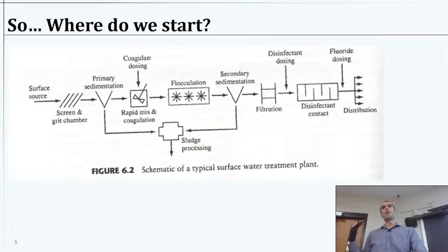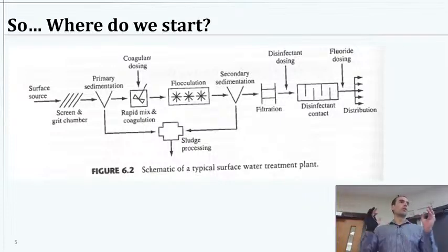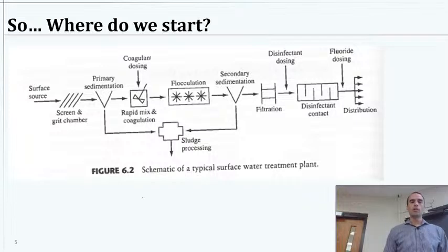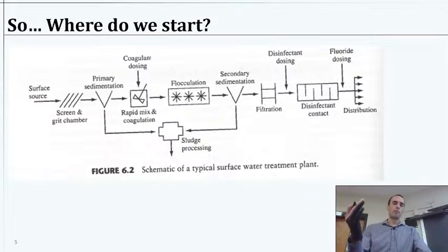And then from there, we can move into, all right, now that we have this in here and it's going to cause the particles to stick together, how do we control a system to allow these particles to stick together by design and know that we have some outcome, and how do we deal with that mathematically? So that's going to be coagulation, then flocculation. In flocculation, we are giving the particles time to stick together. Then we've got larger particles, and then we go through sedimentation again.